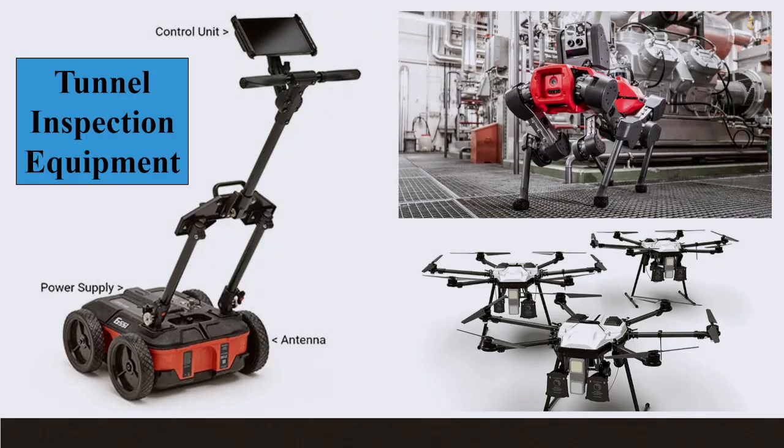I'm not sure how familiar you are with these ones available. The left-hand side one, that is a GPR. This is, again, $40K. So it's basically, you push that. That could be used in investigating the quality of asphalt, the quality of base, quality of sub-base, embedment of utilities, pipelines, electric cables. So a lot of applications. Again, it is penetrating the surface.